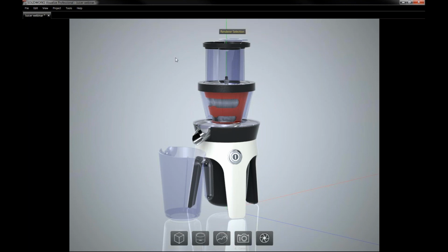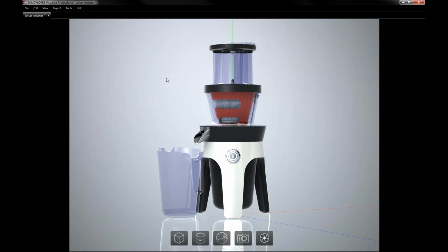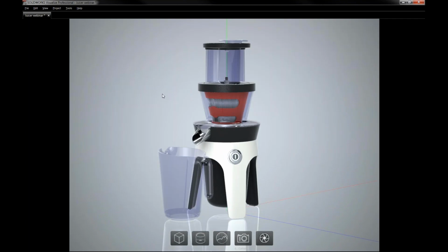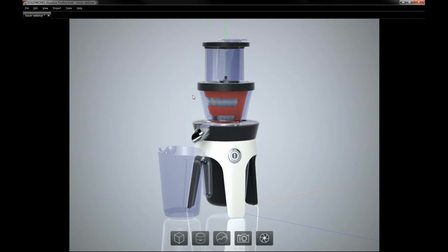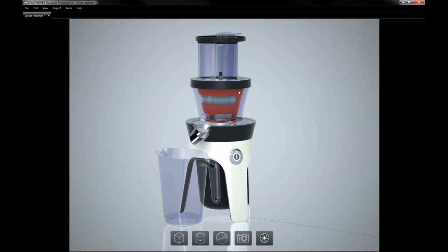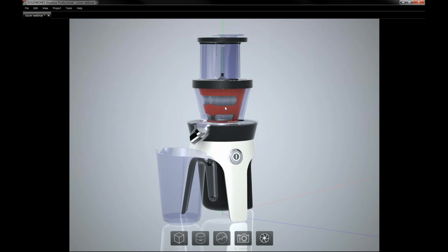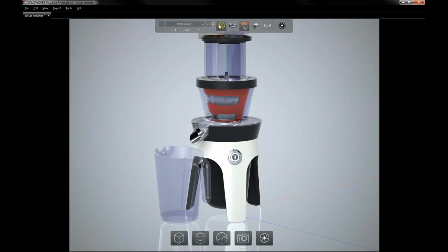With Preview selected, as you see it's selected right here, Alt and a variety of the mouse controls, the mouse buttons, will rotate the model. So Alt and left click rotate, Alt and middle mouse button pan, Alt right mouse button zoom in and out, and Alt and actually scrolling the scroll wheel changes my focal length, as you see there. So in preview mode, everything updates in real time, meaning I don't have to wait for anything to render or res up, as I call it.